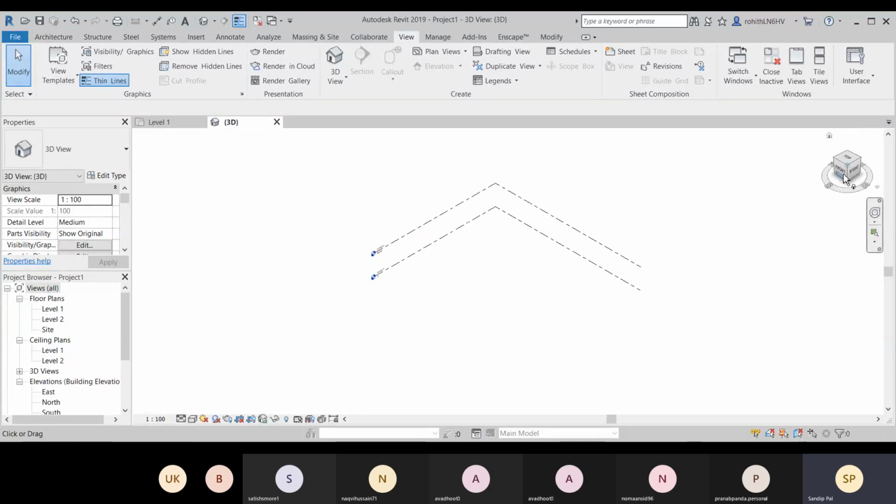And here you have these top corners. With that you can switch to any particular isometric view, and you have this edge, so you can see these two views together. And if you click on any corner, you can see three views together, that is your isometric view. And right now this is the front. So by default the south view is the front view, that is the default option.